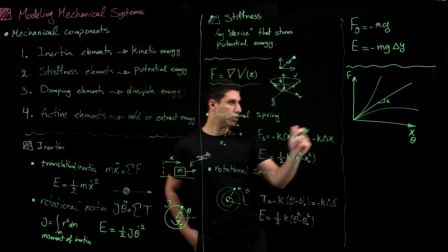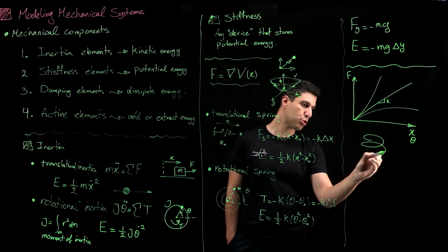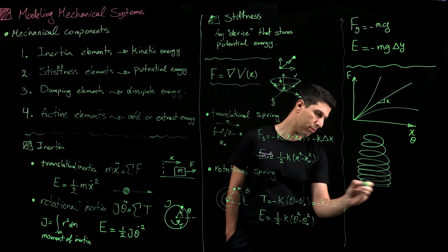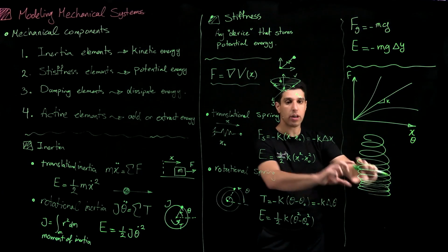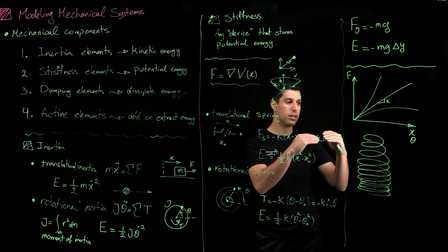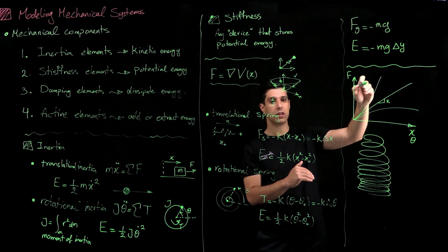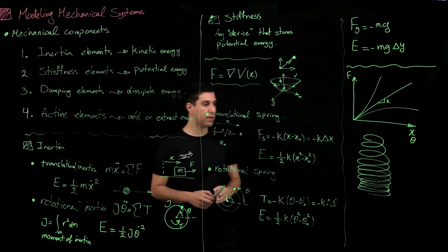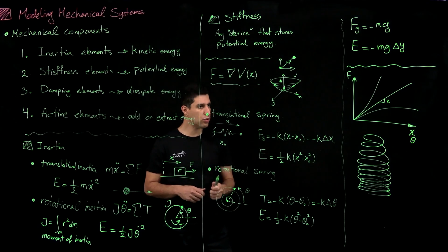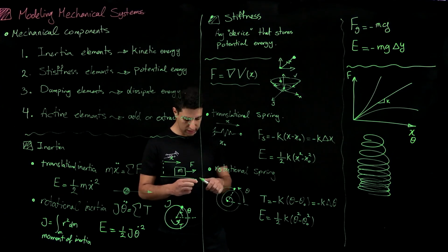An example of such nonlinear systems, you can construct those very simply. If you have a spring where the distance between coils becomes smaller, so as you press it, the coils start to come in contact with each other, and essentially they become ineffective in the rest of the response. So as you push it, the spring force becomes larger and larger because now you're acting at a smaller distance. So this is an example of a nonlinear spring that I think is used often. Maybe in automotive. No, those are mostly linear springs. But anyway, this is a very simple way to construct a nonlinear spring.